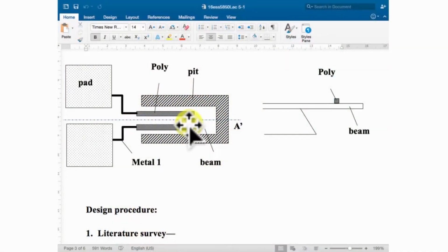So same as this main structure, you need to design and really draw them down into what we call the layout. You have the dimensions of those structures, and you want to draw them using the software onto the real ground, layer by layer, because the fabrication is masking, one mask by one mask. So different materials are on different masking levels.